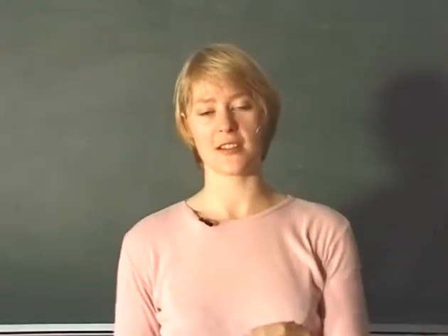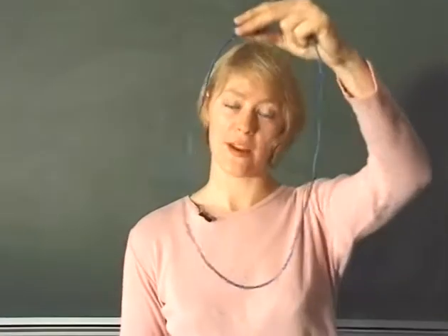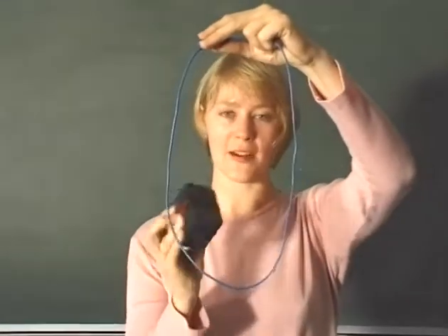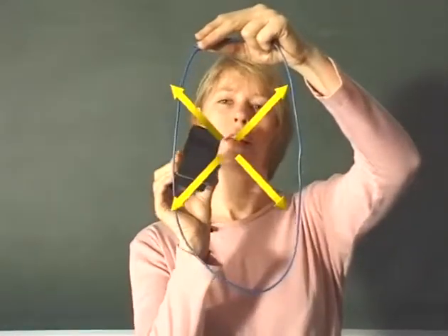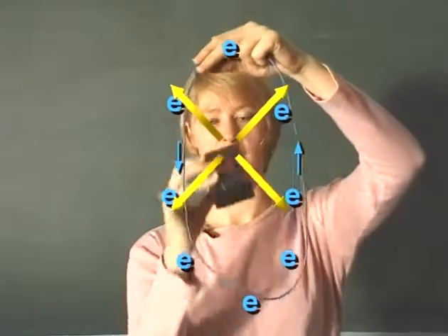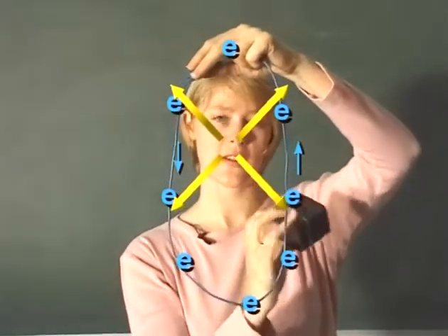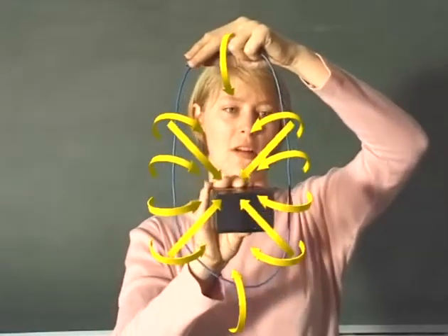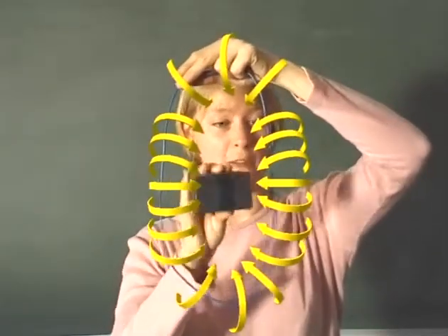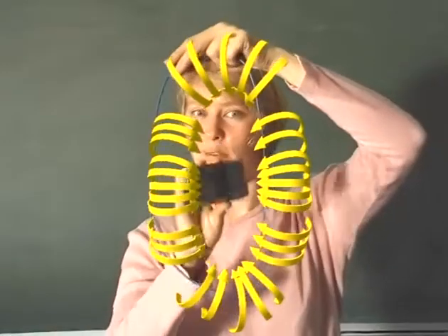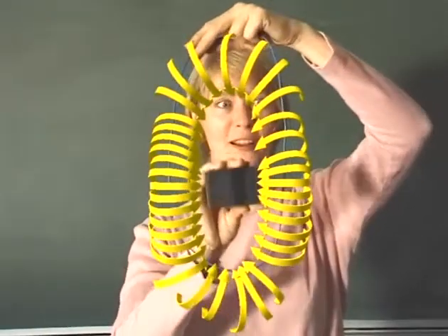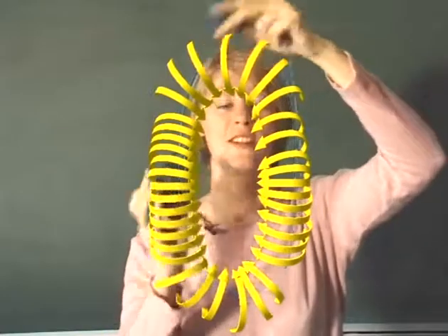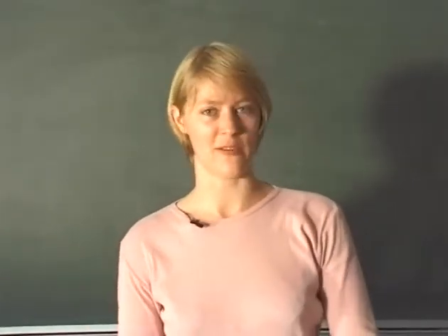So which direction does the induced EMF flow? Well, we can think about it. If we have our magnet moving through a conductor, then that induces an EMF in the conductor, which induces a magnetic field. Now, if that magnetic field would add to this magnetic field, then that would induce a bigger EMF, which would induce a bigger magnetic field and a bigger EMF and a bigger magnetic field and an even larger EMF until it just blew up. So obviously that just couldn't happen in our universe.